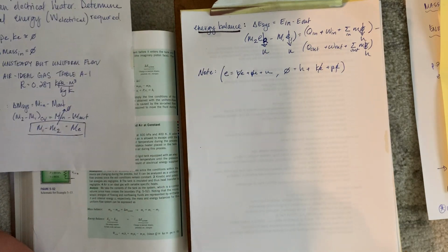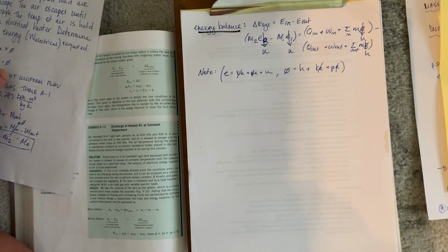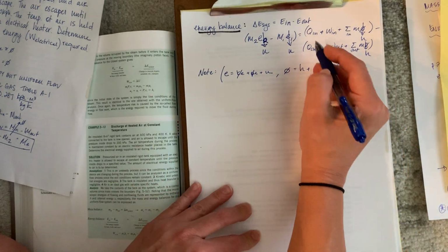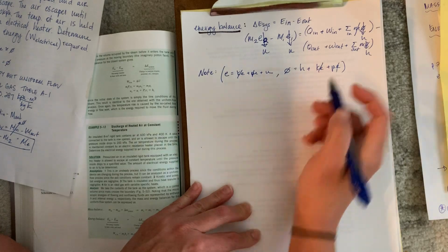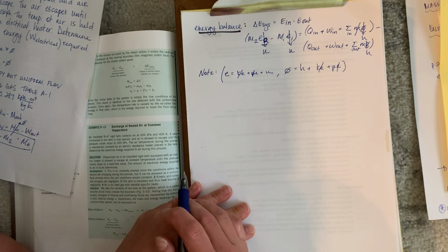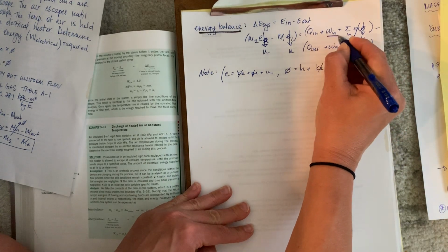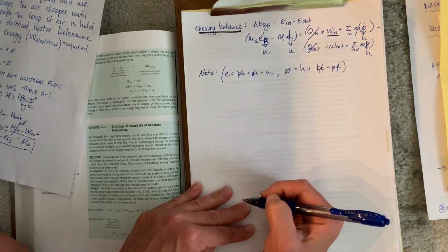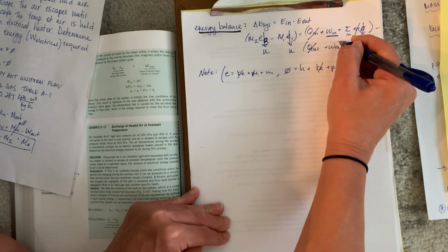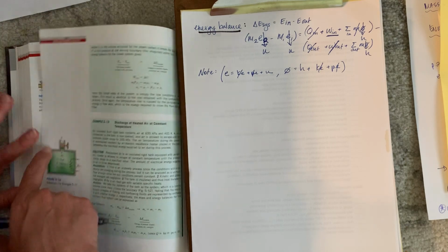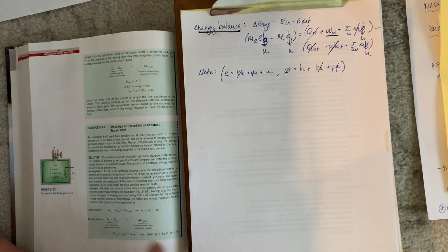All right. We are also assuming that we do not have any mass coming in, which means that this entire side of the equation here is canceling out for some of our mass flow coming in. We know we have work coming in. This is in the form of electrical energy, but we are an adiabatic system, well insulated, no heat transfer occurring. We also are not making work by capturing some of the energy coming out of this valve. We're not putting this into a turbine or anything, getting any work out. We only have this electrical energy coming in.